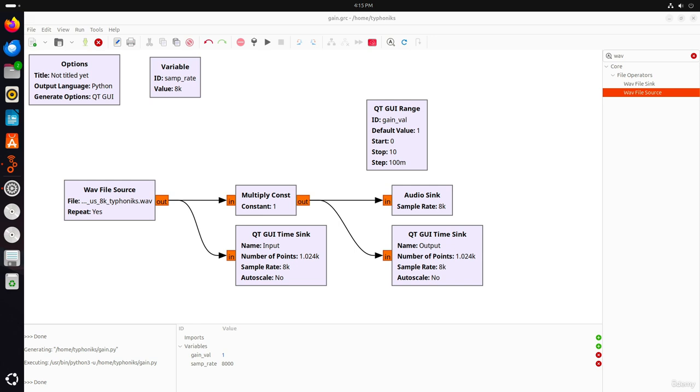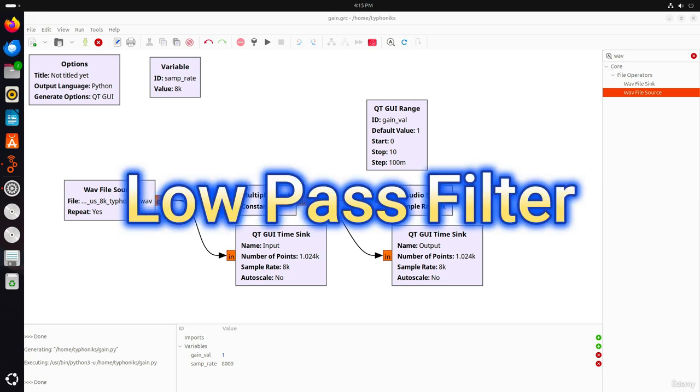While this is the theoretical ideal, real-world filters aren't perfectly sharp and may allow some bleed between the passband and stopband. There are four primary types of frequency-based filters, each designed for a specific purpose. Low pass filter, LPF. A low pass filter allows frequencies below a certain threshold, the cutoff frequency, to pass. It blocks higher frequencies. A common use of a low pass filter is for removing high frequency noise from a signal.